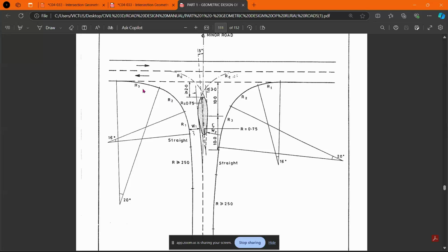And of these radii, remember R2, for a vehicle that is 30 meters, you require around 13.5 meters turning radius plus an overhang of around 0.5 or something like that. But ideally, we work with R2 being anything above 17.5 will allow your vehicles to be able to turn at that point. When you're talking about R1, you can be talking about anything that is above 20, 25.